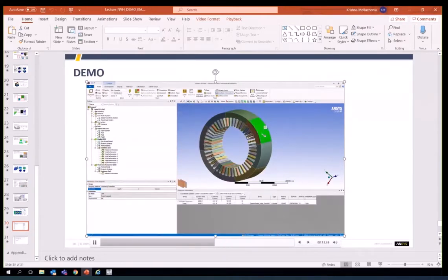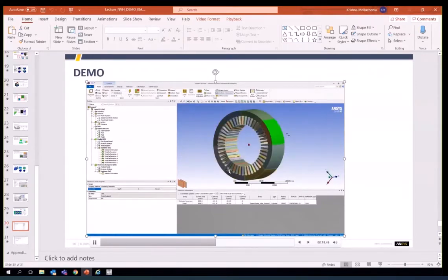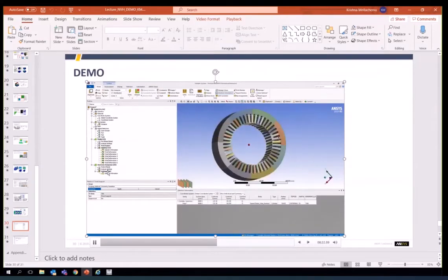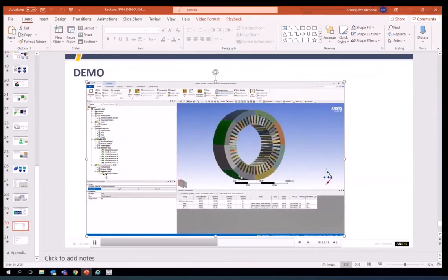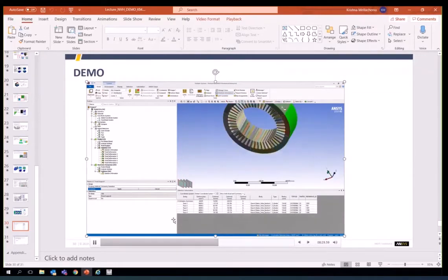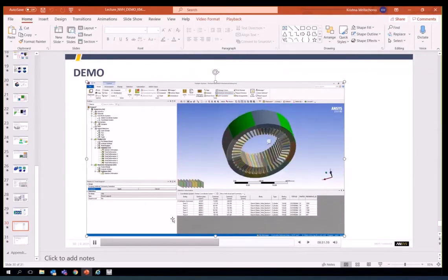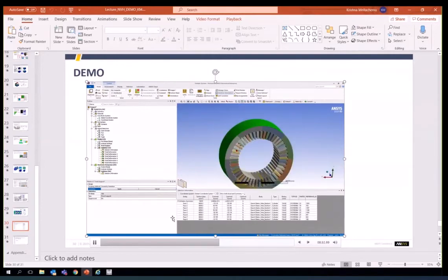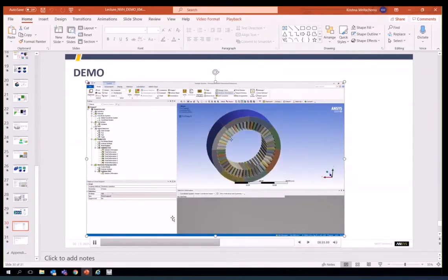In this analysis, we are going to be fixing the outer surface, assuming that it is fixed, and use the modes from this modal analysis for the harmonic response. So we are just selecting all the outer surfaces to perform the fixture and do the modal analysis.